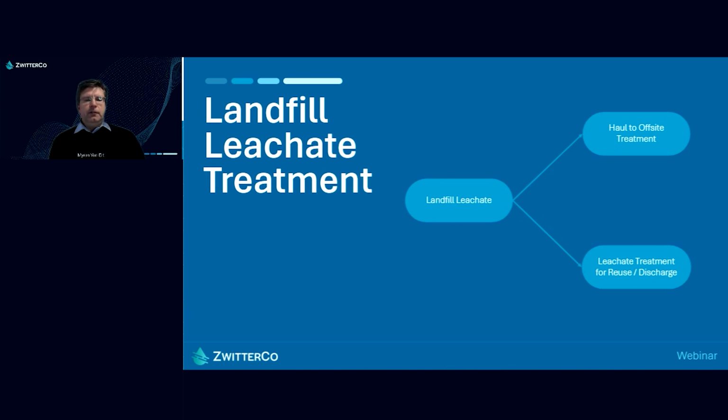Although the volume of leachate is relatively small for a POTW or other processor, the nature of the high-strength stream, such as those heavy metals, those organics, nutrients, notably PFAS and those other related compounds, may present a challenge for that given POTW or processor and could be a further challenging situation in the future as well. As a result, trucking costs, distances, tipping fees, and all are increasing and becoming more difficult to manage.